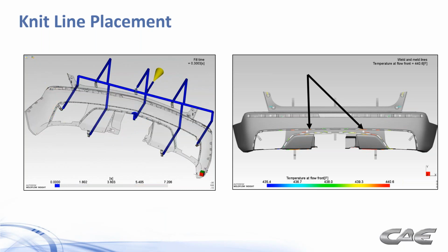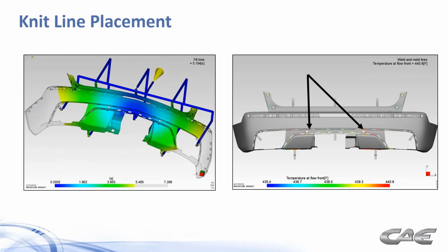Yeah, and again, as analysts, we're trying to create the largest possible injection molding processing window. And so many people try to push the envelope, with part design too thin, too few gates, not wanting to spend the money on an extra hot drop, whatever it may be. All of these things contribute to making your molding window smaller and smaller. And I get it. It's a good thing to push the envelope, but don't be surprised when you push it a little too far, right? So use the technology to get you to a point where you've got a satisfactory molding window without pushing the envelope too much.